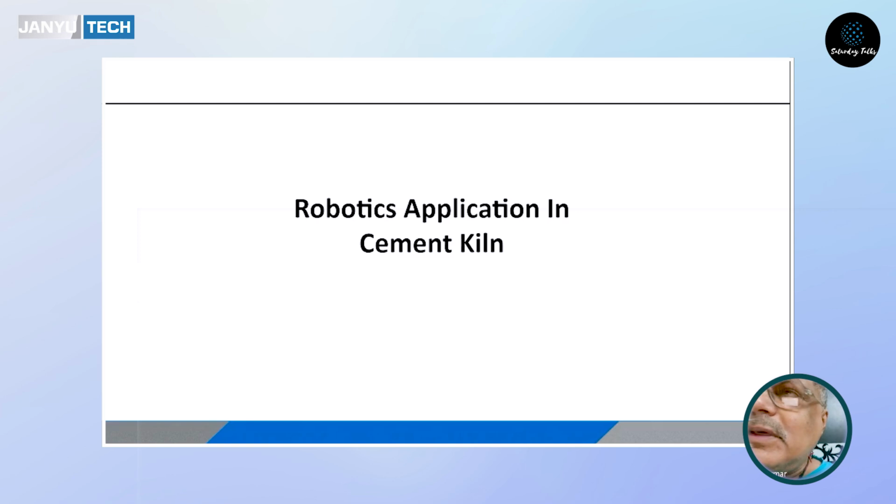So whatever moisture is there in gypsum or slag, and even the little moisture absorbed by the cool clinker, which is very less, 0.5 to 0.6%, when ground in the mill at that temperature of 90 to 100 degrees, that moisture evaporates from the system.